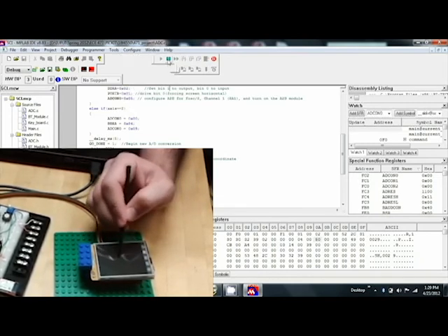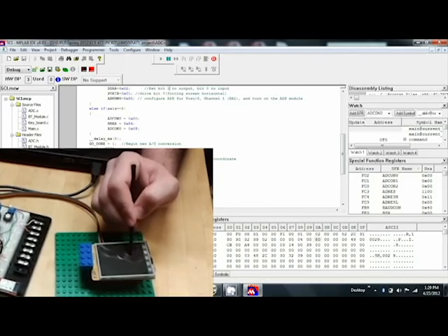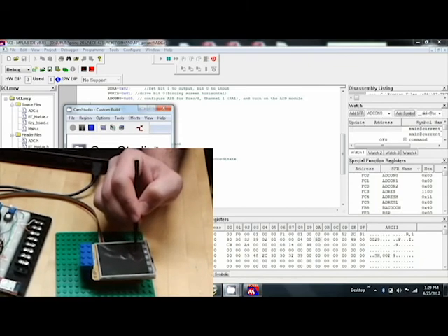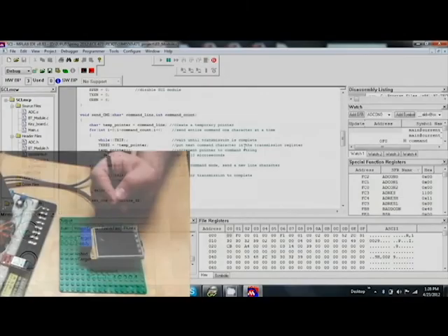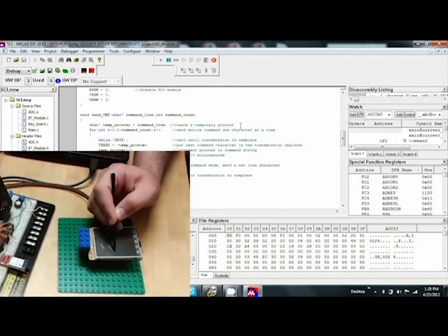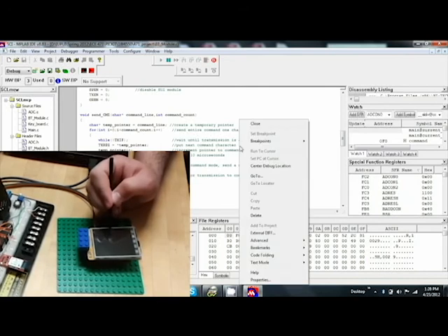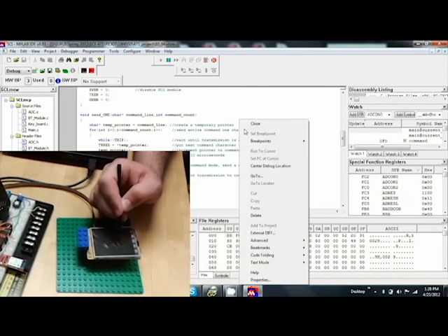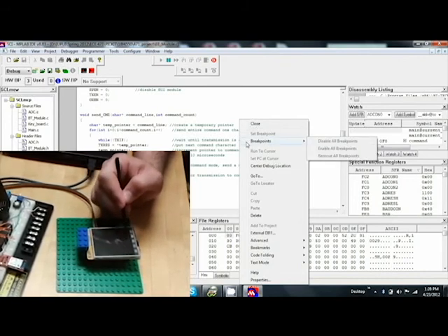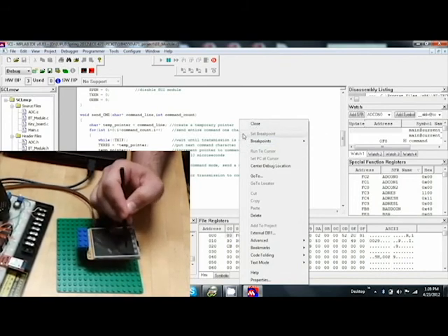In addition, we have also programmed logic which will track the stylus if it remains still. If the stylus remains still for an extended period of time, a left mouse click will be sent to the host computer. If the stylus stays still for a longer period of time without being removed from the screen, a right mouse click will be sent to the computer. It is important to note that these controls are not sent until the stylus has been removed from the screen.